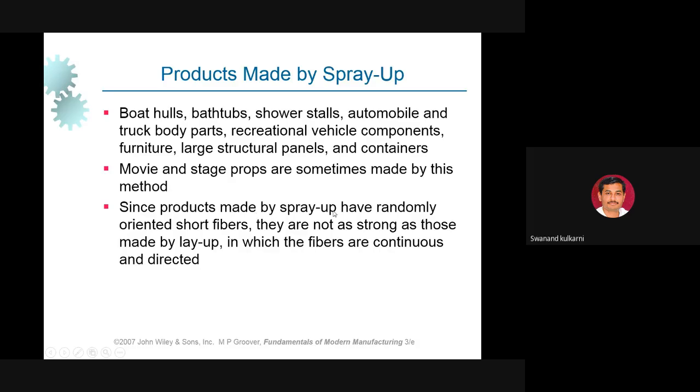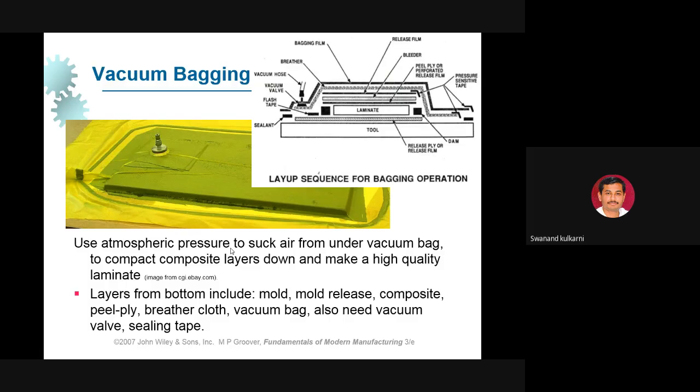Since products made by spray up have randomly oriented short fibers, they are not as strong as those made by layup, in which the fibers are continuous and directed. Is it okay? So here you can see how this spray up technique is used.